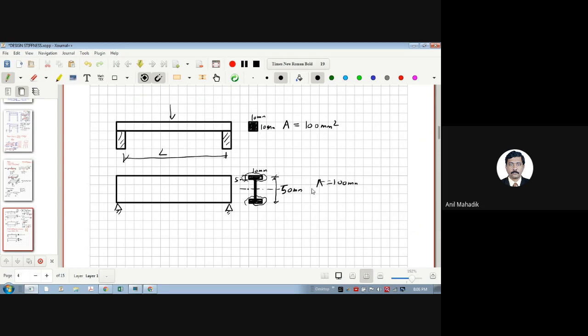So this and this area is same, but this mass is arranged away. So in the flange area, I have more material. So flange area is more, let's say. So have you seen the section sizes in steel table before? You will see the thickness of flange is more. कभी भी देखो steel table में. Yes, sir. tF is more. Okay.